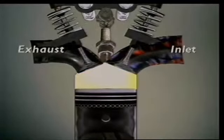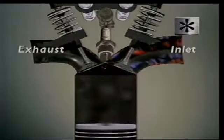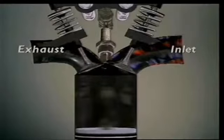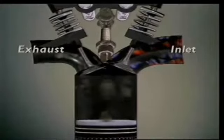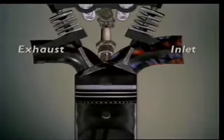Both valves stay closed as the piston leaves bottom dead centre. The piston moves up, squeezing the air-fuel mixture into a smaller and smaller volume, which compresses it. That makes its temperature rise, and that makes combustion easier. Just before the piston reaches top dead centre, the next key event occurs: ignition. Burning, expanding gas generates the force to push down the piston. This is the power stroke that drives the engine. The piston now moves from bottom dead centre to top dead centre. The exhaust valve opens and the piston pushes out the leftover gases.